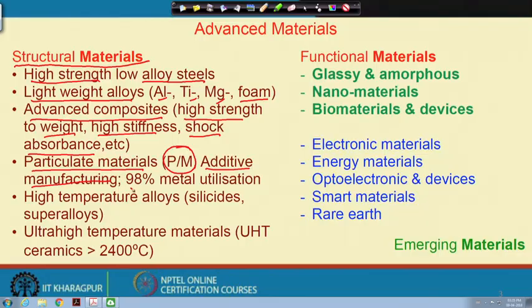There is definitely a large benefit of additive manufacturing over the conventional casting process, because we know the pre-desired shape, we do not need any risering. Like in case of casting, almost 40% of the metal becomes useless because of cutting down of the risers and different gating systems and so on. Therefore, additive manufacturing has become very popular these days, where 98% of the metal could be utilized.